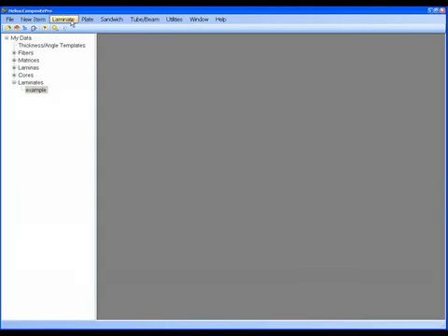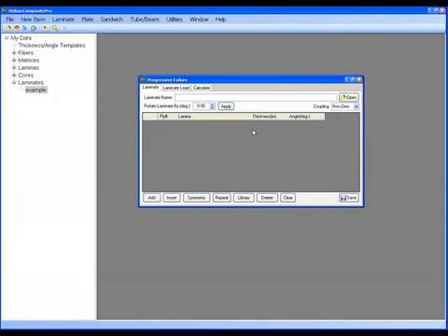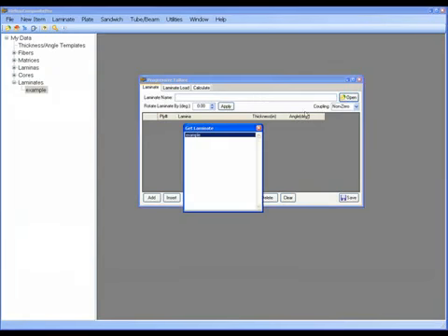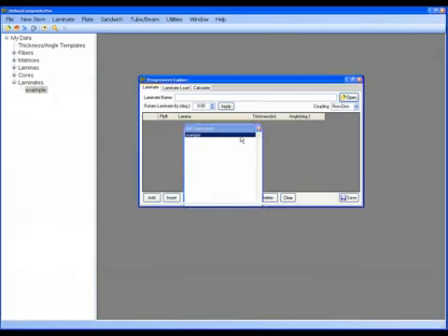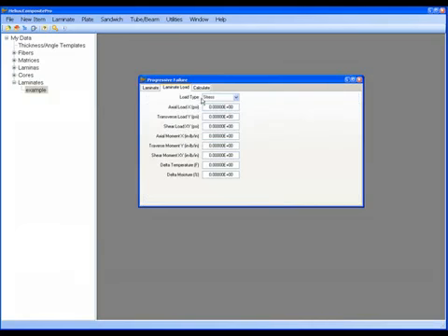In specific here, we are looking for, let's say, progressive failure. These are some of the advanced features that 4.0 has. I'm going to use my example laminate to demonstrate these. We'll go over to laminate load, and let's apply a load of, let's say, 200 KSI to this as a resultant stress.